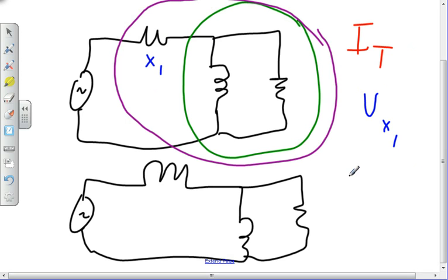With that, we find the voltage across the parallel path as being the voltage source minus the voltage across X1. And then with that, we calculate the currents through the other guys. And if we have to calculate powers, we'll do that too. All right, so that's the plan. I'm sticking with it. Is there anything else going on? Chapter 12. Yeah, that's about all there is.